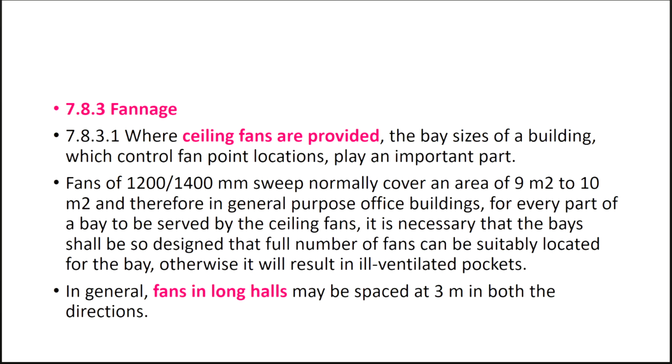That is why, because you are planning for certain fan hooks with respect to the size of the room. This is just to tell you that one fan will cover around 9 to 10 square meters. So we need to plan how many fans are required to be provided, maybe in a long hall. Again, it specifies that in case it's a long hall, you have to provide these fans at 3 meter spacing in both directions. Although not directly related to you, this information will help you out.